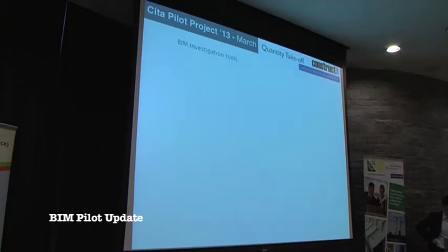Right? Just in terms of BIM investigation tools, I'm starting to use Autodesk Navisworks to pull the models in and to do model aggregation, pull in the structural and the architectural models.